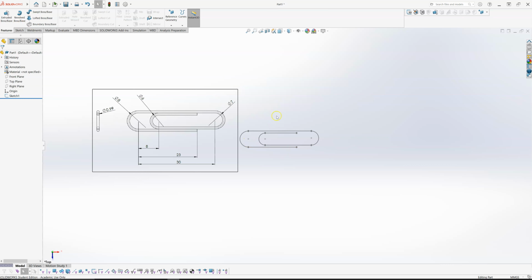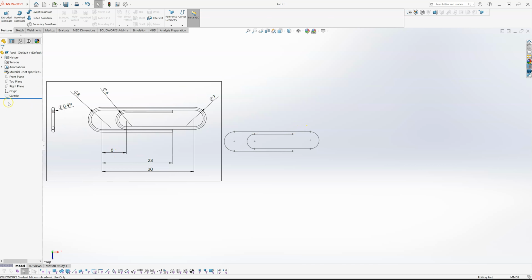So what that means essentially is we're going to take an area. You could draw a separate sketch here. For example, I could sketch the cross-sectional area of this wire and extrude that circular area along a curved path. Now the curve that we sweep it along doesn't have to itself be closed off like you normally would have with a sketch. It's just a guide curve for the extrusion or for the sweep.